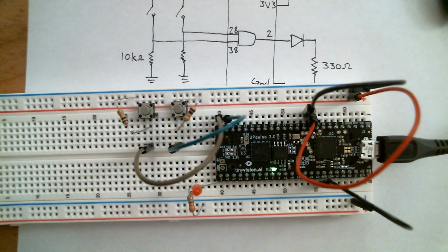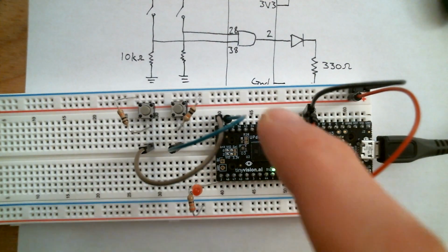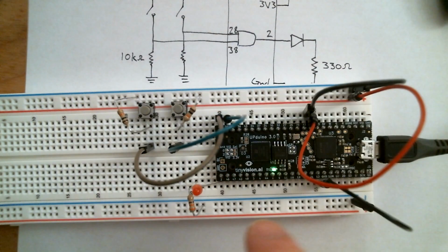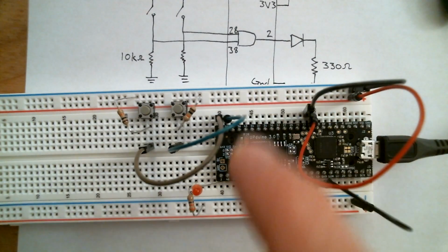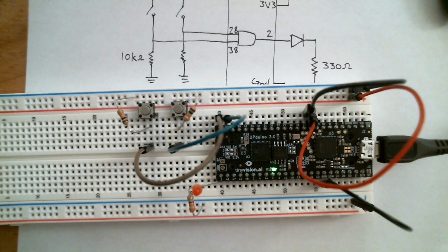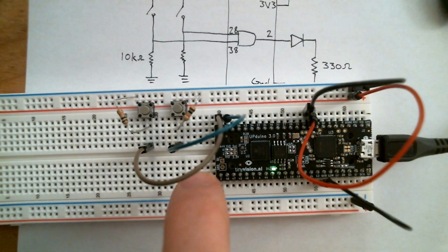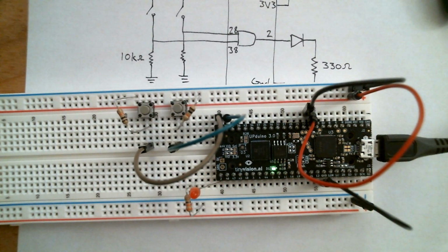You could even try creating a simpler circuit in icestudio where you just connect the input directly to the output and confirm that one of the buttons is able to toggle the LED on and off. And finally, you might confirm with a multimeter that the output is toggling high and low, and you might, again, check that the LED is put in the correct way, and so forth.